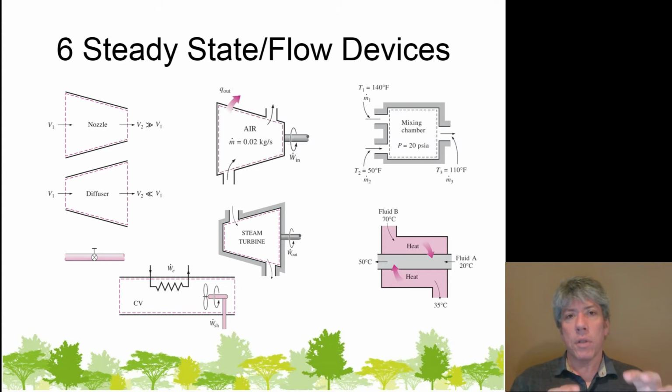And did you know also that after the air is compressed, it's actually pretty hot and needs to be cooled down before it goes into the engine so that the engine doesn't destroy itself by compressing that air again? And so there's actually a heat exchanger called an intercooler that takes the hot, compressed, pressurized air and cools it down with more outside air, not by mixing it, but by running it through a heat exchanger so that you can maintain the pressure of that compressed air before you put it into the engine. So that's an example where, yeah, some of these devices do make things a little bit fun.